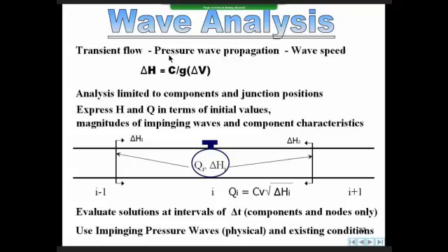Now, the wave analysis method, I was fortunate enough back at Carnegie Mellon when I was studying that I had a very brilliant professor who got up and talked about transient flow. He said, well, you close a valve, you generate a pressure wave, it travels at sonic speed. When it gets to another valve or a pump or a junction, it will be reflected and transmitted through that.